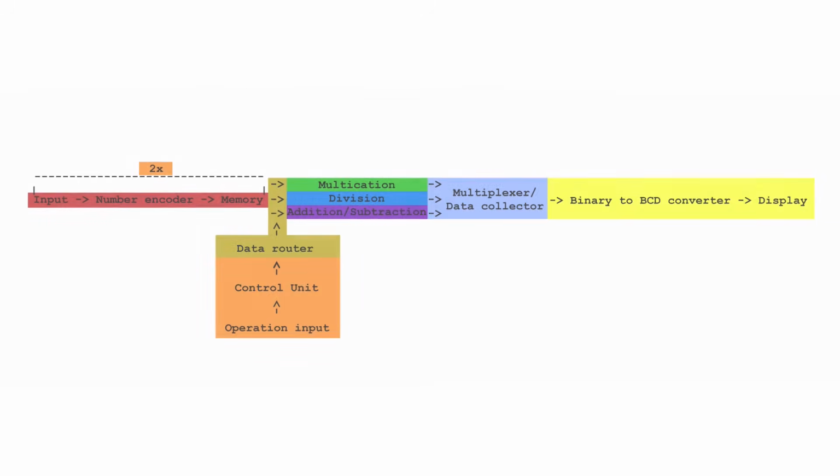Going back to a block diagram, everything begins at the number encoder in memory. The first thing the calculator does is take a number input, such as 99, and encode those button presses, 9 and 9, into binary. It then stores the 8-bit number into the memory, and the system waits for an input from one of the operation buttons. Once one of those buttons has been pressed, it repeats the process of taking another new number and encoding it before sending it to the calculated memory.